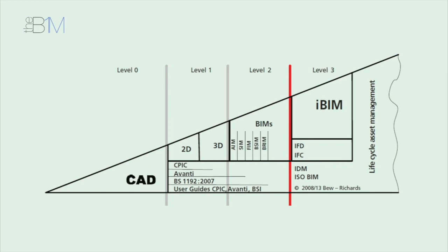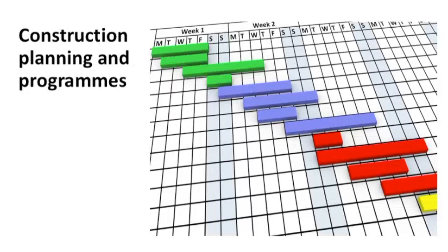It's quite different to the BIM maturity levels that run from 0 to 3 and beyond, describing the supply chain's ability to exchange information in a digital way. 4D, 5D and 6D considerations can all occur within BIM Level 2. If you're working with 4D BIM, it would be wrong to say that you're working at BIM Level 4.